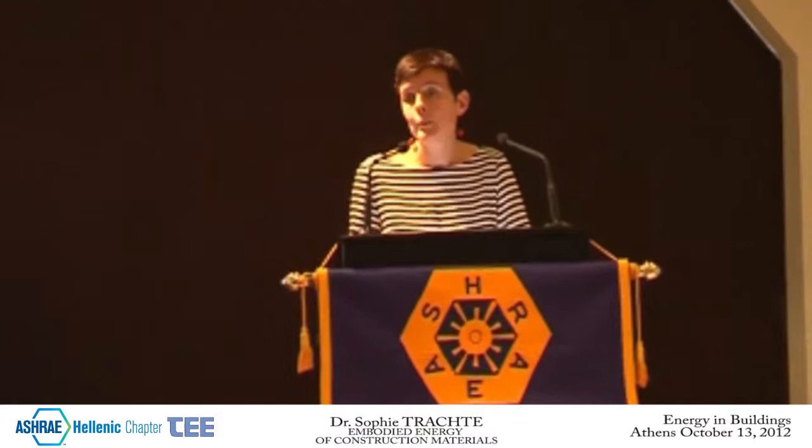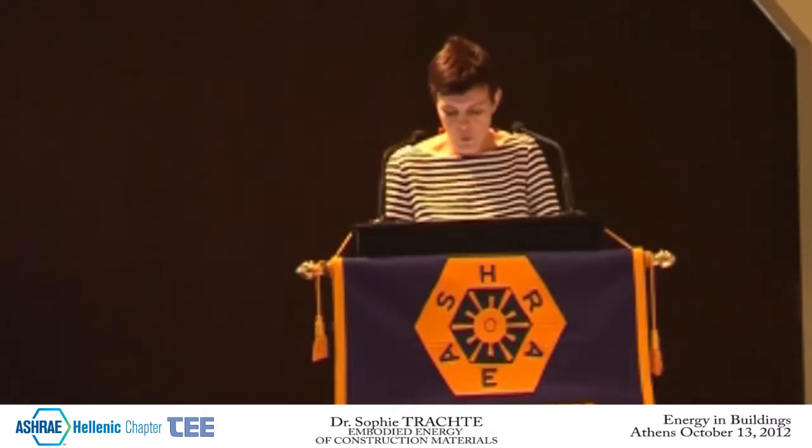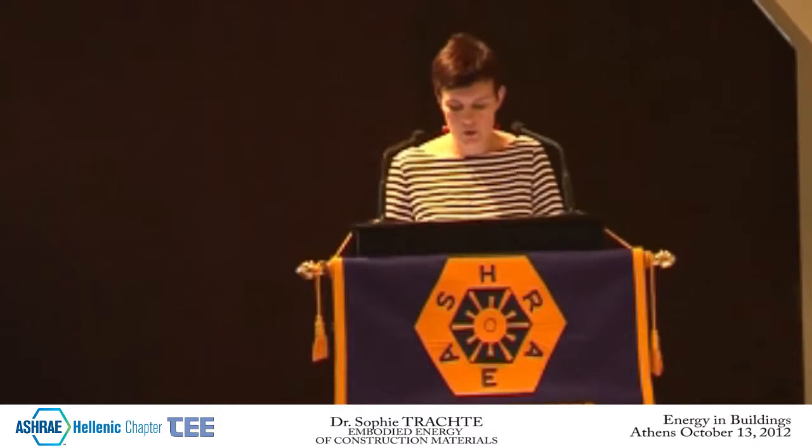And grey energy is a more global concept about energy used for building materials. Grey energy is the energy required for all the transformation undergone by a product throughout the life cycle. It could be divided into 5 types of energy: renewable energy and non-renewable energy, but also what we call energy materials. So this is the energy stored by the material, and this energy could be recovered. And also the energy process used for all the operation of processing, transport, and so on.